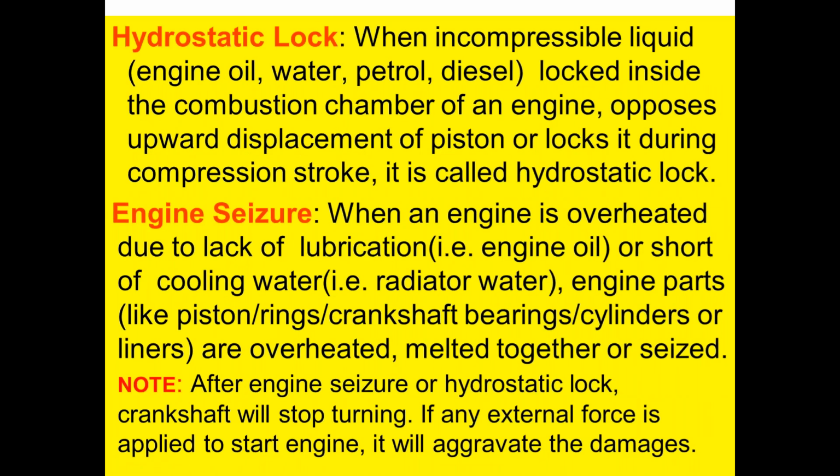Hydrostatic lock. When an incompressible liquid, maybe engine oil, water, petrol, diesel, whatever, is locked inside the combustion chamber of an engine, it opposes the upward displacement of the piston or locks it during the compression stroke. It is called hydrostatic lock.